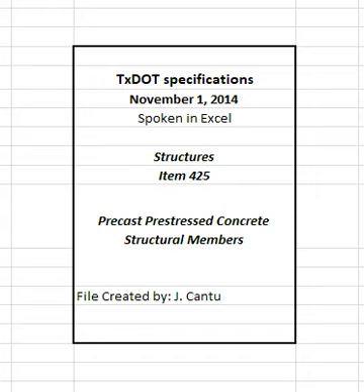Protect traffic against falling objects during the erection of diaphragms and other structural members, during the placing of cast-in-place concrete, and during the erection and dismantling of forms when railroad or roadway traffic must be maintained beneath beams already placed. Protect traffic with nets or flooring with openings not larger than 1 inch or as approved.